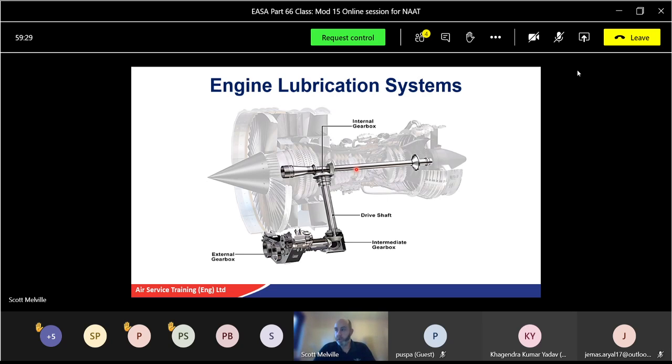Now that's actually a triple spool engine there, but if you can just have a look where it's connected here. So you've got a gear here, and a gear there. That's attached to this compressor. And so it will be a high pressure. Always a high pressure. There's your intermediate, and then the LP here as well. So it'll always be a high-speed gearbox, high-pressure spool.